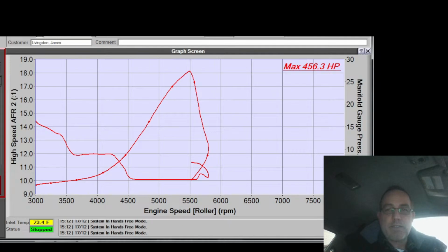And that makes more sense because the VE at idle is usually 55 to 58% on stock cams, sometimes as much as 60 on stock cams, and that's what I had. And the fact that it was 12% too much tells you no, something's wrong. So I changed the injector data, and bam, fuel trims are now 0.0 right now. So that is good news there.